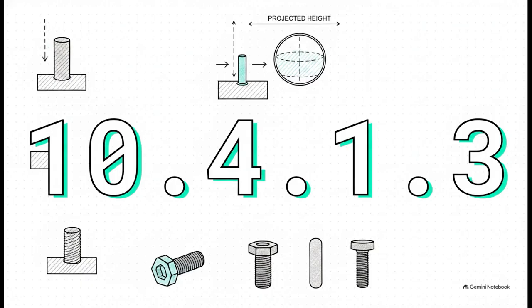Not just the mating part thickness. You have to account for the entire exposed length of that fixed pin to guarantee it's never going to bind.